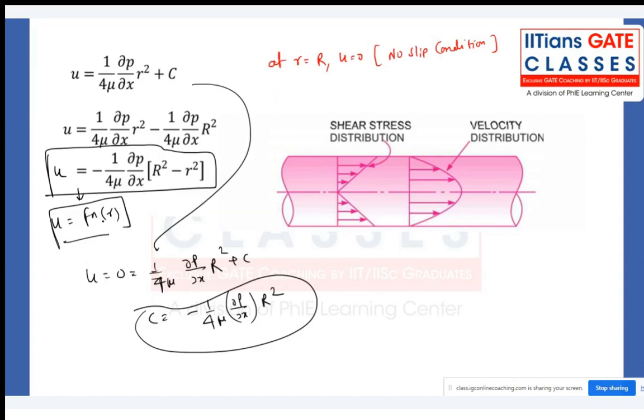Have you ever thought why we use only centrifugal? Of course, why would you think about it as an aerospace engineer, but still, when we have many pumps, why are we using specifically that one? We are using it because it can handle a huge mass flow rate, or it can send a very huge discharge at a particular section, right? But suppose you are sending water in agriculture, there you will see the reciprocating pump, because there we need to send the water from the very ground level to the surface level. So we need a high pressure ratio, not a huge amount of water discharge.